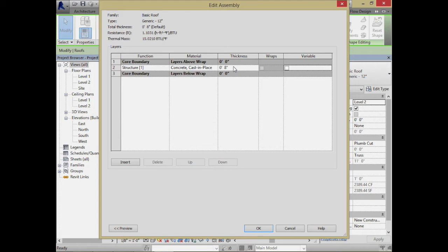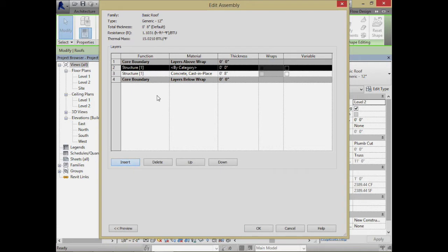We tend to have some sort of drainage layer, a little bit of air space in there, so that the water that percolates down can go off and head into other places. That might be sand and gravel, or some sort of barrier that's keeping the earth and keeping clear space underneath it, so you have a very clear channel for the water. But there are probably some other layers, and we just really need to think, even as you're thinking about building a green roof, about what system you're going to put in there.